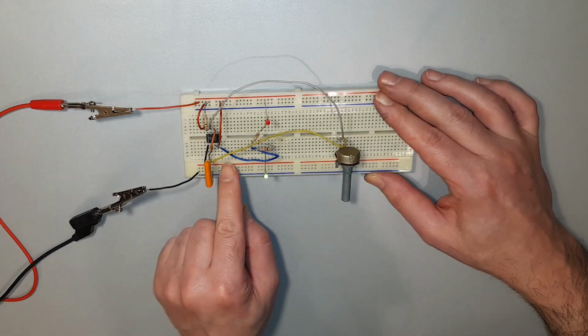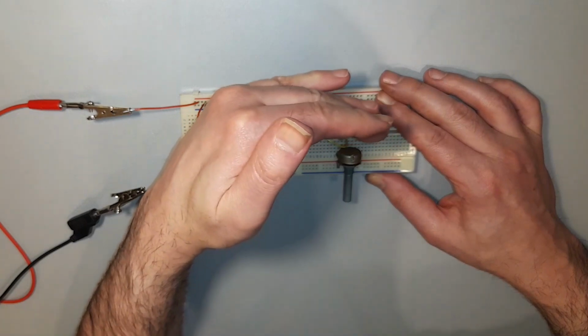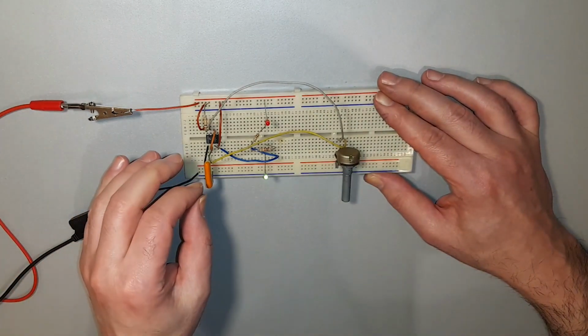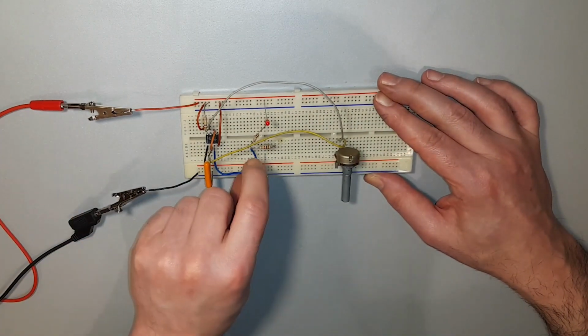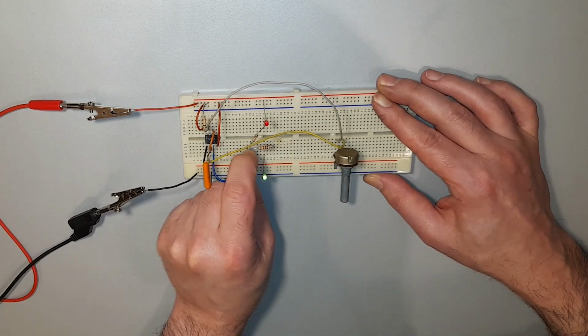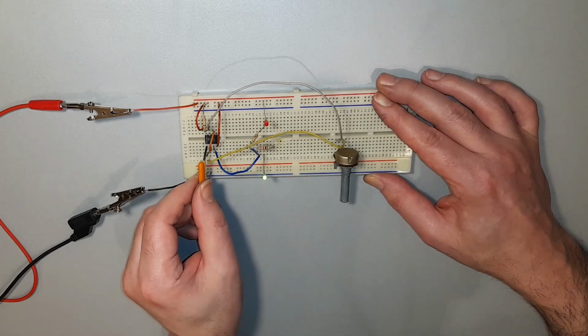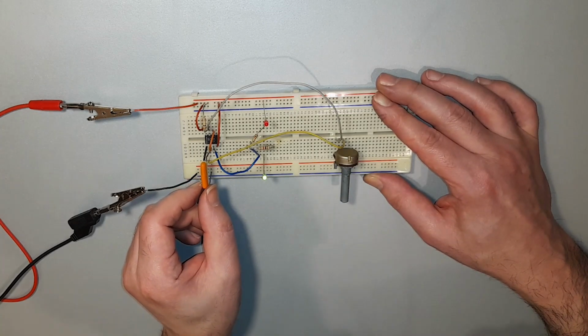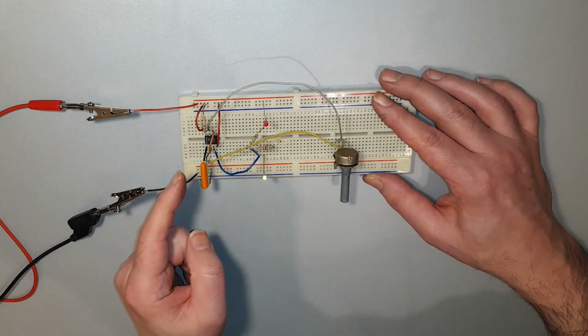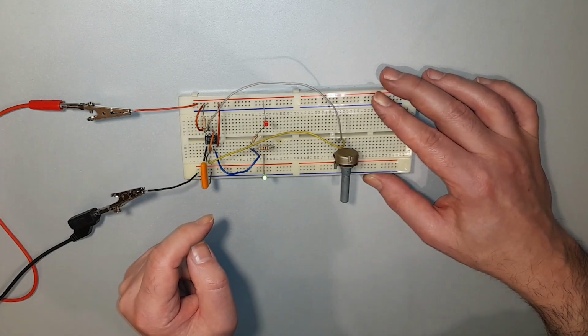Removing the blue wire from the output, pin 3, to the LEDs simply puts both LEDs in series with the power supply and makes them both have the same current flowing through them. So that does not account for the asymmetric light output from the two LEDs when they are connected to the output of the 555. Have you figured it out yet?